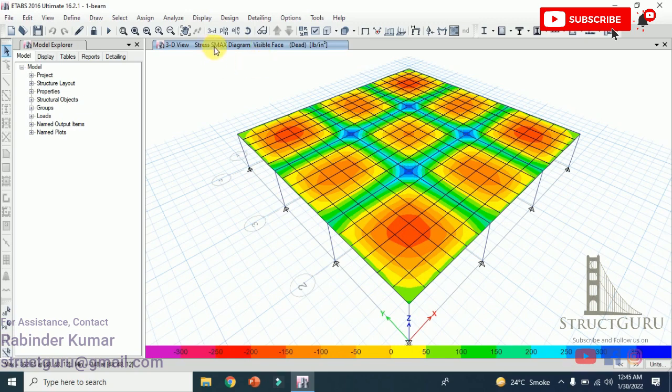From the analysis results we can conclude that whether you model it separately or collectively, it does not affect your analysis results. However, it may affect the design results, because in an actual structure the slab may be used for different purposes. For example, the same slab is used for corridors, sometimes as a cover to a room, sometimes for classrooms. For different occupancies we have different loads, and the different loads give us different thicknesses of the slabs.